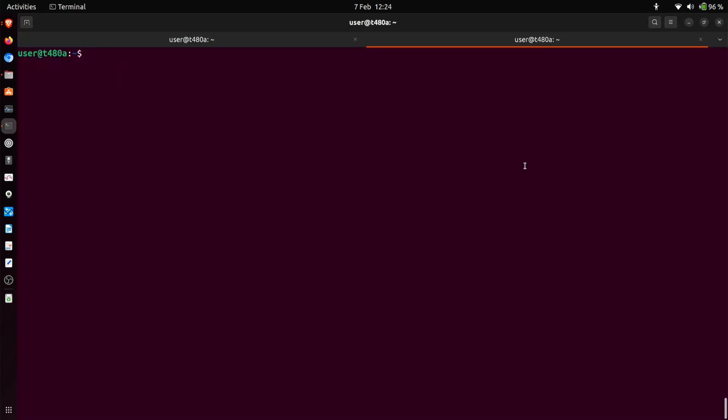So the Raspberry Pi has had time to start up now, and if you look at the Ethernet connector, the yellow and green lights come on after a while and they flash occasionally. It shows us some activity. So I'm going to try now to connect to it using SSH from the terminal, and you can also do this with Windows from the command line or Mac OS. So I'm going to SSH into the username is user